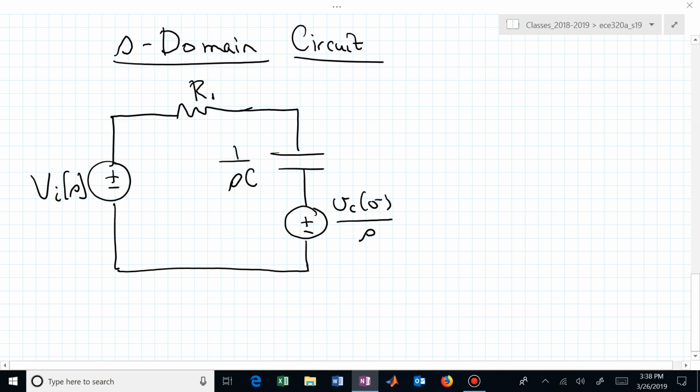Then we would say, well, there was also an inductor, and that inductor now has an impedance of S times L. And we're going to derive where these come from, but now we can simply start re-sketching that original circuit, and now we actually have a voltage source that accommodates or accounts for the initial current that's flowing in that inductor.